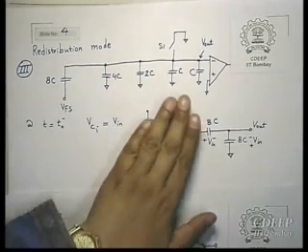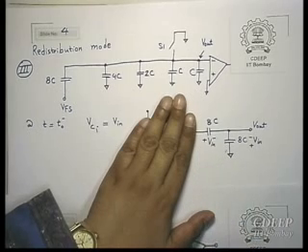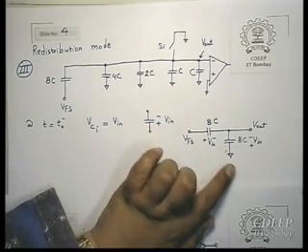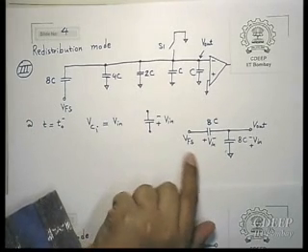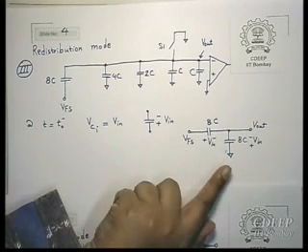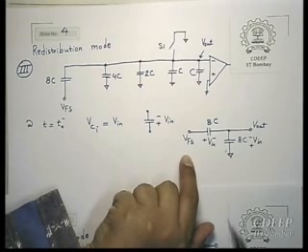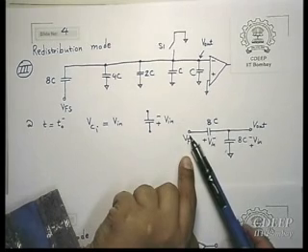If you ignore full scale, the summation of voltages in this loop is 0, right? Therefore, adding V full scale doesn't change the value stored on the capacitors due to Vin. It only changes the value stored on the capacitor due to charge distribution, as a new event due to the change of this voltage to V full scale.